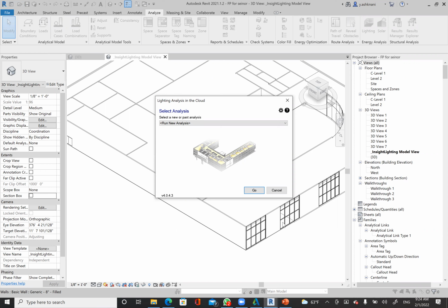So the panel schedule will come after the looping is done, and for every panel we can put a panel schedule, and after that we can connect the transformer to the panels. So we will have the panel schedule, circuiting, and the looping plan for lighting and receptacle both.